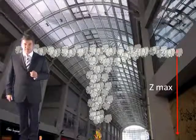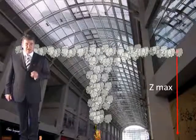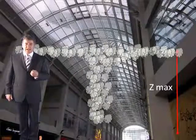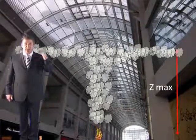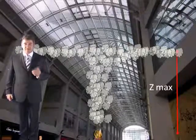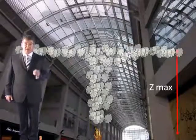Let's move on to step 5, the stratification check. Now in this case, because the clear layer height is 24 metres, we need to consider the Z max, in other words the stratification point. We have to make sure the smoke is not going to stratify and fail to make it to the top or to the ventilators. That's what you've got to try and work out now, Z max, and this is going to work out whether or not the smoke is likely to make it to the ventilators.